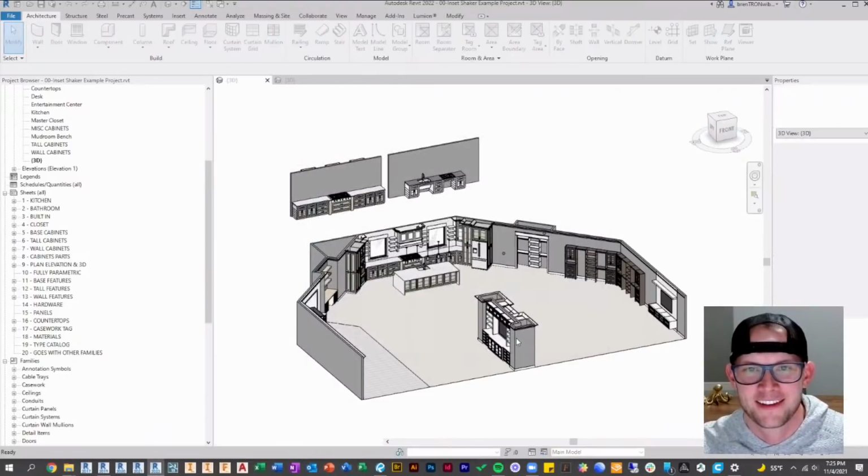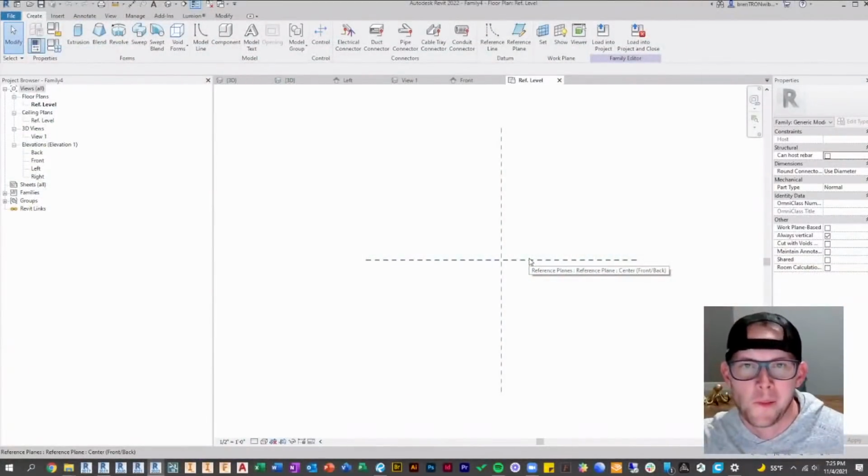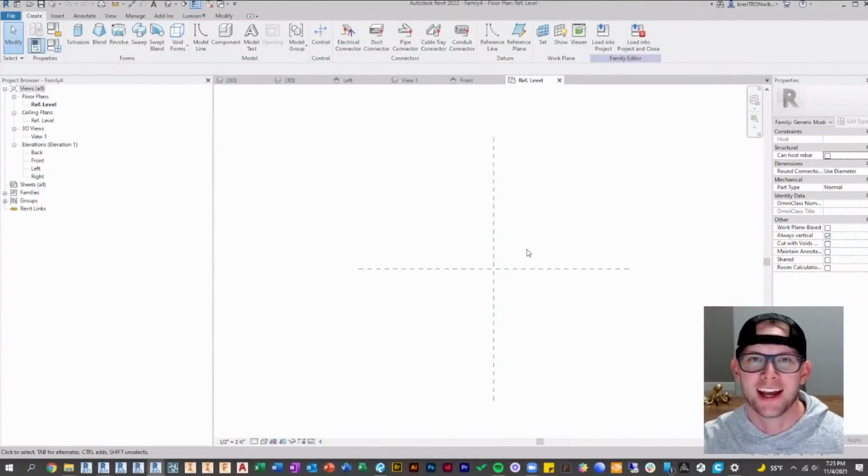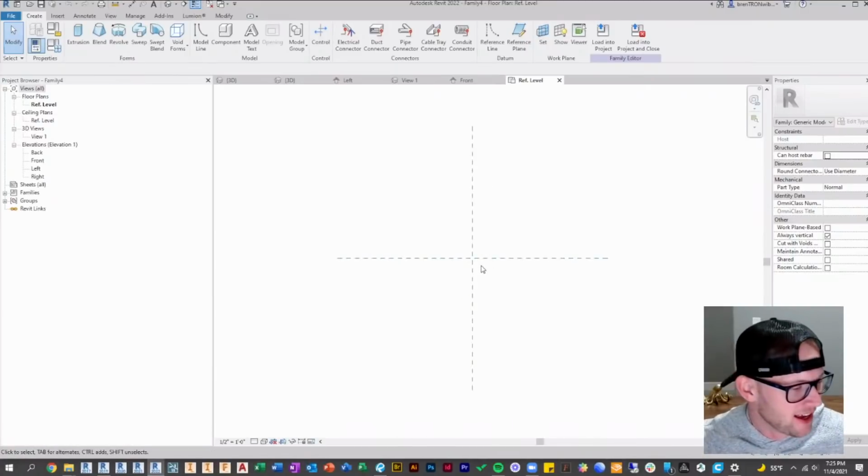You're starting with a standalone generic model. And if you start with a hosted object, you are kind of stuck. So that's a great tip in and of itself: starting with a generic model and then converting it afterwards if you need to. And Paul Oben has a pretty good workaround if you accidentally have something hosted and need to get it back unhosted.